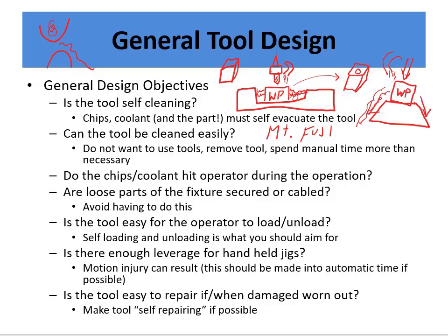That seems like a basic thing, but you would be shocked at how many tools have little pockets or areas that are not easy to clean. And if you don't do this kind of design, you're going to spend a lot of time cleaning the pocket that catches all the chips. And any of that time is really waste. It's not value added, okay? And that non-value added time has to be paid for. The customer is going to pay for that, but the customer doesn't want to pay for non-value added activity. Either that or you're going to pay for it, and it's going to eat into your profit margin. So you don't want to do that.